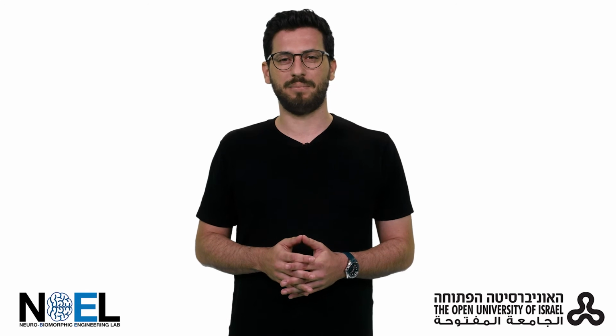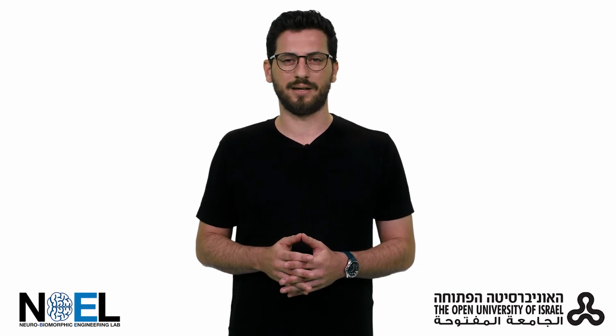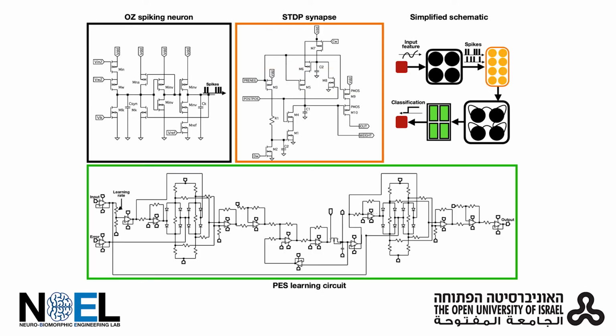Our circuit design comprises 3 main modules: the OZ spiky neuron, the STDP synapse, and the PES learning circuit. The analog design of the OZ spiky neuron comprises a voltage-to-current transformation circuitry and a voltage amplifier spike generation circuit. OZ produces a spike train in accordance with its tuning curve, or defining rate-input current dependency.